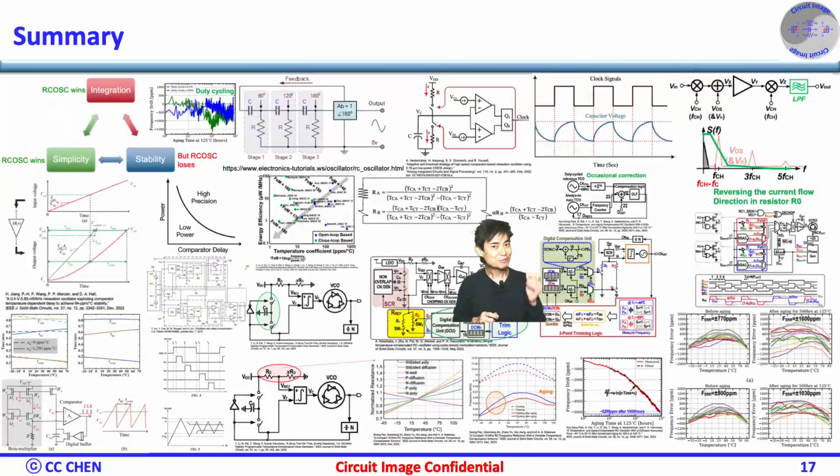Here is a summary image showing you why you may need RC oscillators. Intuitively, they are small, cheap, and fully integrated. So, with smart techniques, feedback loop, switched resistors, calibration, you could possibly achieve 100 to 200 ppm stability in CMOS.